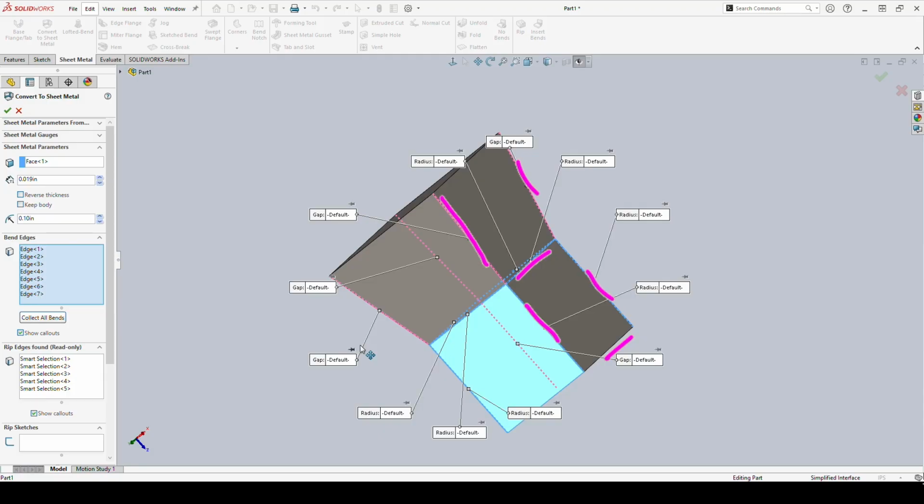Am I going to have pieces that are overlapping that shouldn't be overlapping, or things like that? You can actually get this guy to work out even without having this face here. So the obvious way is to have this face and everything comes out from it. But you can sometimes get SolidWorks tricked into letting us make something like this. But what happens is the flat pattern doesn't work.